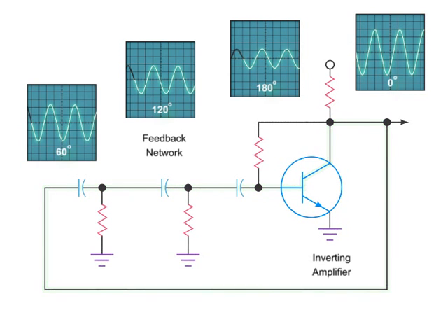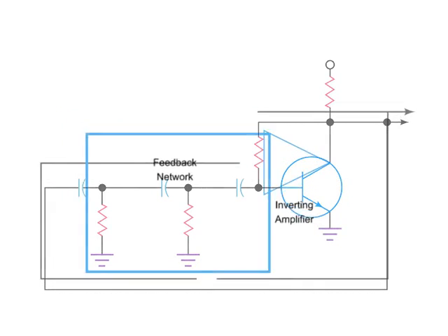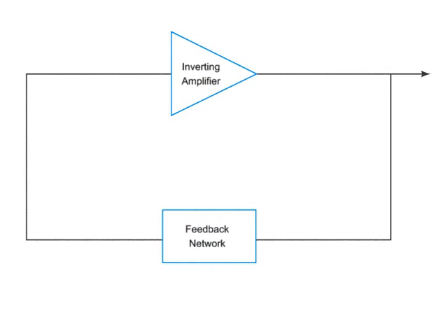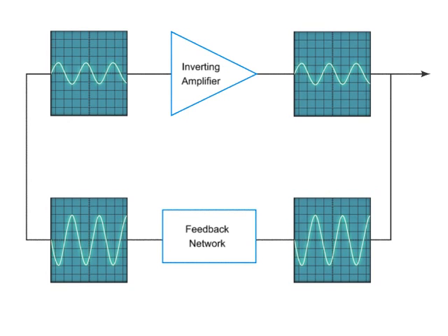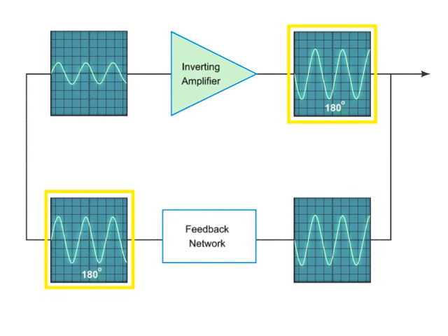In order for the oscillator to produce a repetitive oscillating electrical signal, it must follow two criteria. The circuit must have a loop gain that is greater than 1 and it must maintain its phase state. The phase state is sustained when the inverting amplifier's 180 degree phase shift is reversed by the 180 degree phase shift of the feedback network.